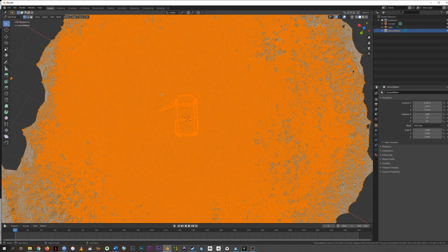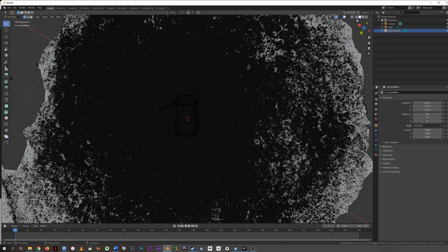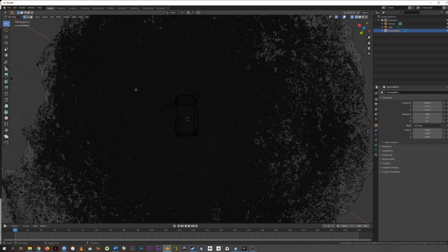So this in Blender allows you to edit the mesh instead of just editing the whole scene, and you're selecting the entire mesh. Now we're selecting all of the little pieces parts. I'm going to change to wireframe view, which is up in the top right here of what's called the viewport. You choose the circle that looks like it's in wireframe.